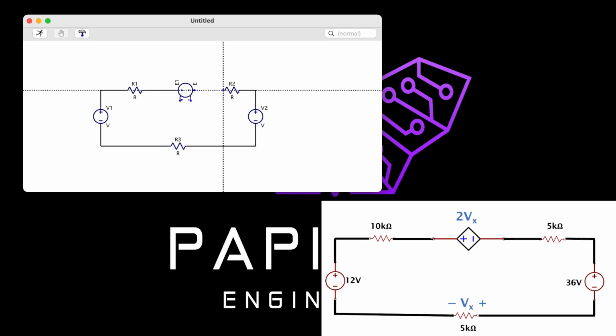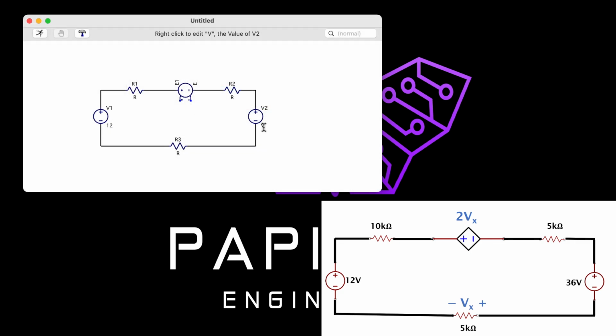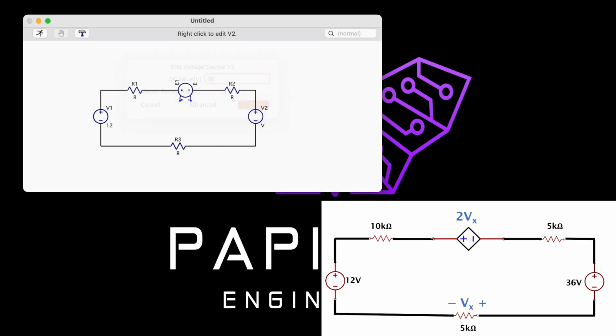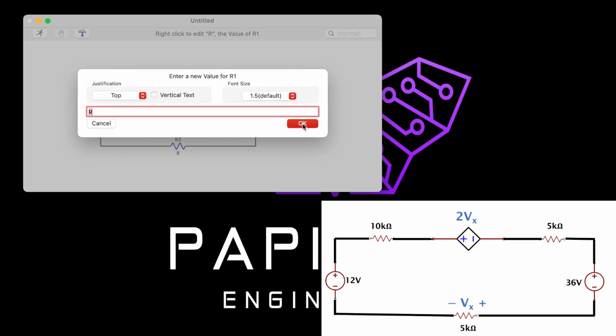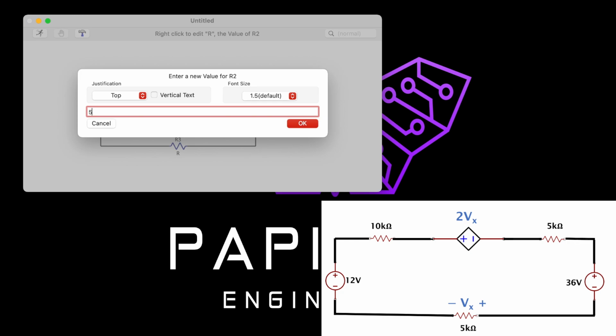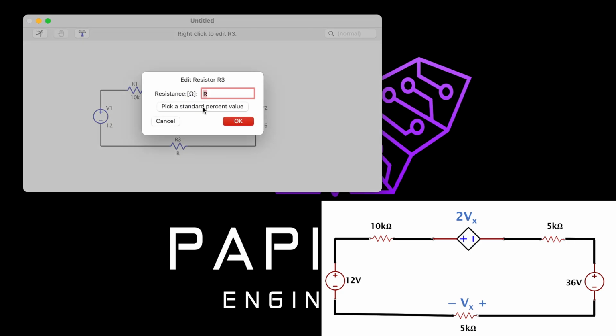So now that I have that, you have multiple options you can do next. You could certainly put in the ground, and if you don't put in the ground, I also love to label or at least enter my values for each component. You left click or right click on each component, and you make sure you're entering in the source voltage, for example, DC voltage source, and not changing the actual name of the component itself. So again, I'm replicating what we have here. What's nice about LTspice, you don't have to write in 10,000. You could literally put in 10K and 5K to represent the resistance in ohms for each of the resistors that we have here. Okay, so there it goes.